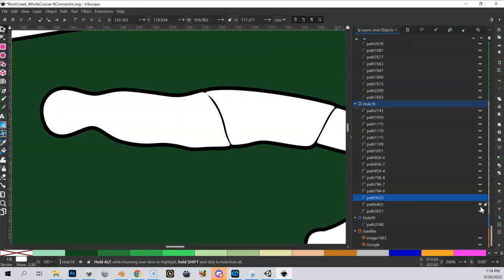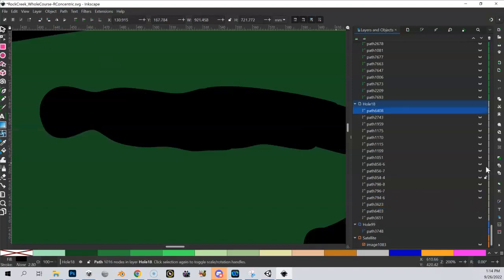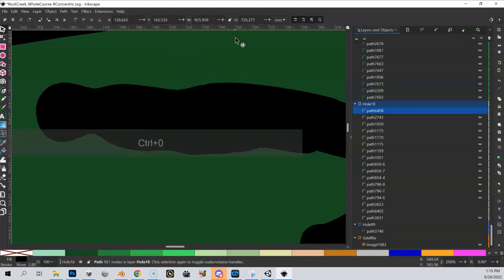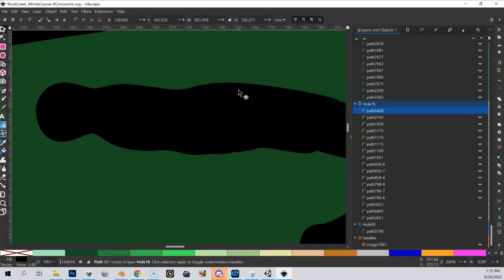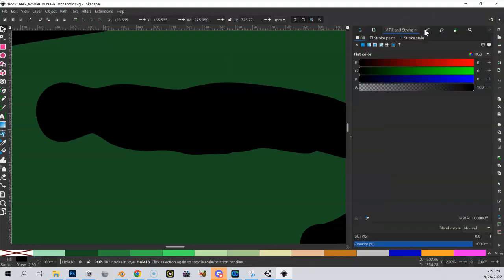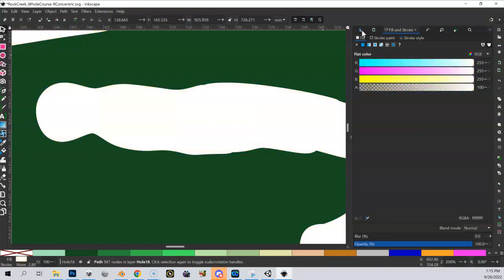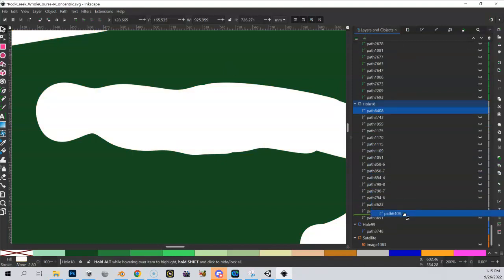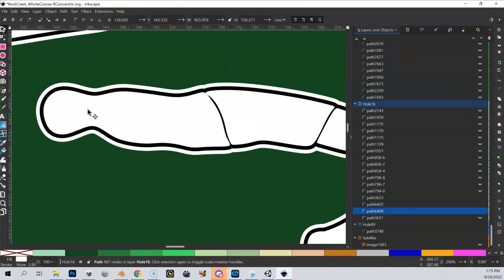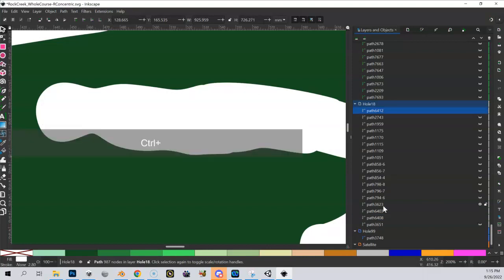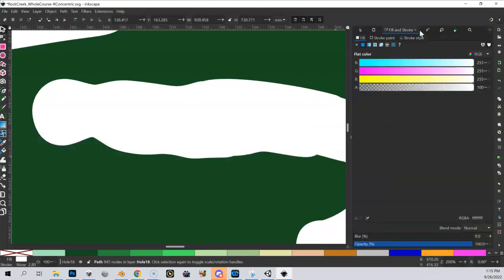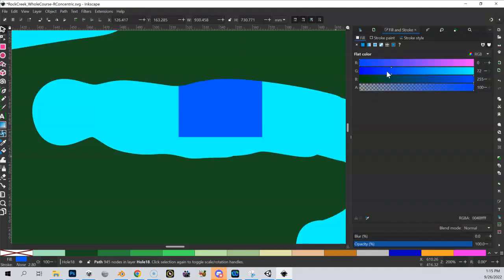So if I select my black one again, which is this guy right here, I do Control D, and then I outset it again, Control ). So that just outset it another 2.25 meters. I come up here and now change it to white. And if I come back and move it down to the bottom here, you can see now I have a white, black, white. And let me do one more. Highlight this, Control D, outset it again, change this to black, so we're alternating essentially black and white back and forth.